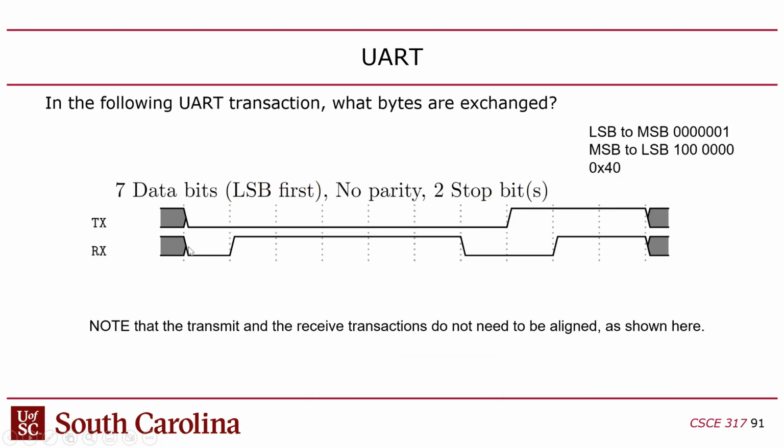And then on the receiving side, coming back the opposite direction, you have the data being sent as 1, 1, 1, 1, 1. So that's 5 1 bits. I'm sorry, we actually had 6 0 bits on the first line and 5 1 bits on the second line, and then a 0 0. So 1 1 1 1 1 0 0. Right, 5 ones, 2 zeros, and then the 2 stop bits. So that's shown up here.